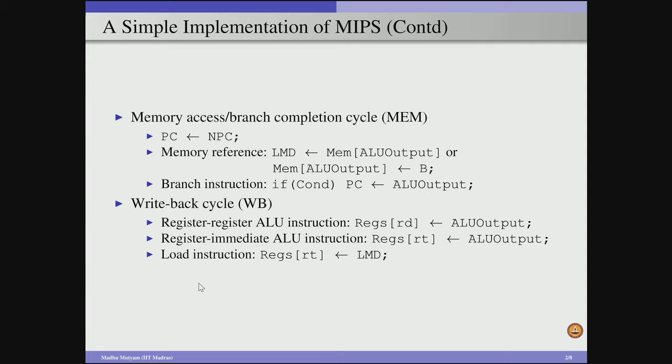Now we are going to see how this is implemented by considering the data path as well as the control path. Before going for the pipeline implementation, we will just consider the non-pipeline implementation of this MIPS data path. By the way, any processor design consists of the data path as well as the control path. The data path gives you the interconnection among different hardware components, and the control path gives you the timing signals to different components, so that these components will perform operations based on some event that has happened or at a specific time instance. So, now we are going to look at the data path associated with this non-pipeline implementation of the MIPS instructions.